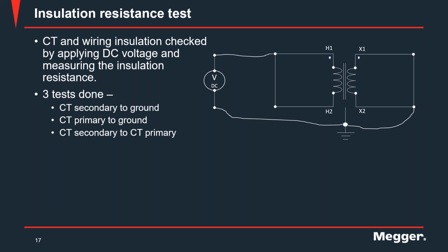If I'm remembering correctly, they established a knee point at the point where you have an increase of 10% in voltage. As you are increasing voltage to get this curve, you are doing increases of, let's say, 10% values, and at the moment that a 10% increase produces a 50% increase in the excitation current, that is where the knee point of the CT is declared. This is the method that the IEC standard uses.